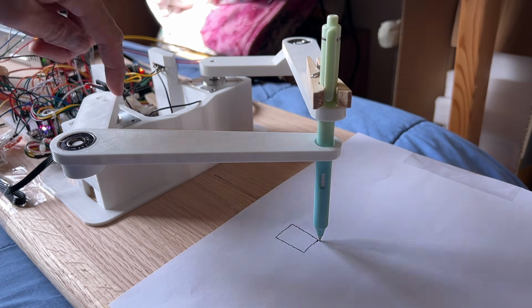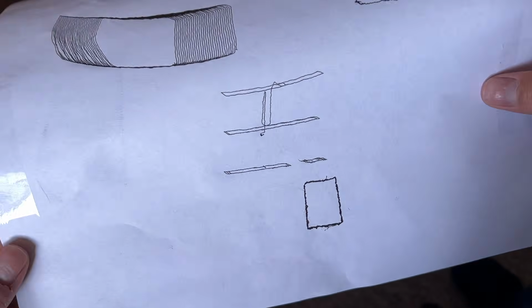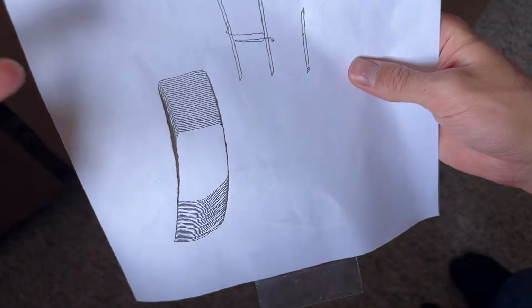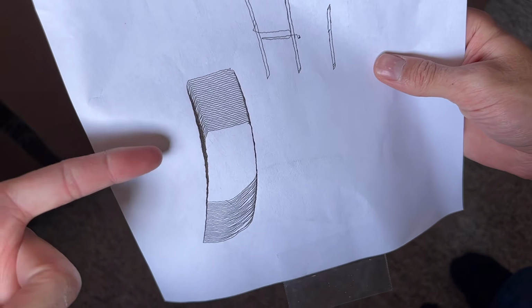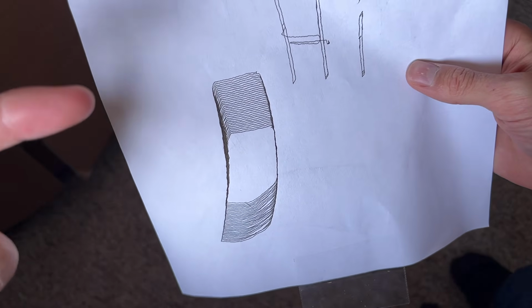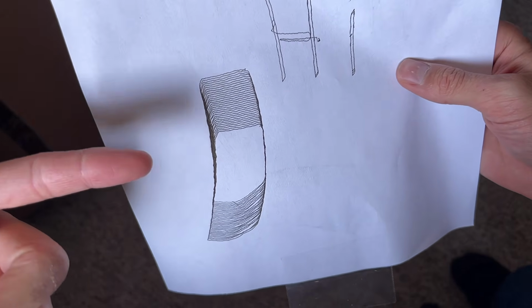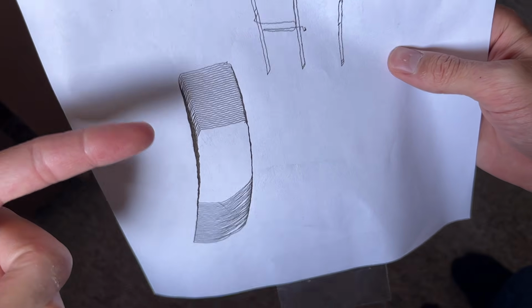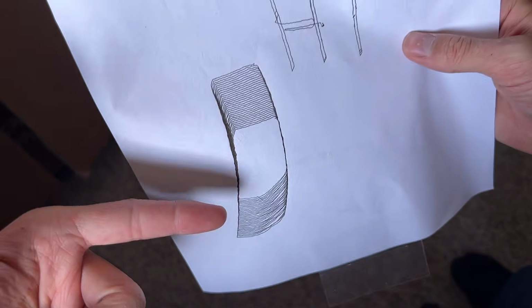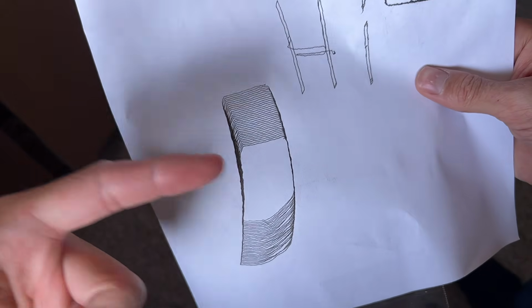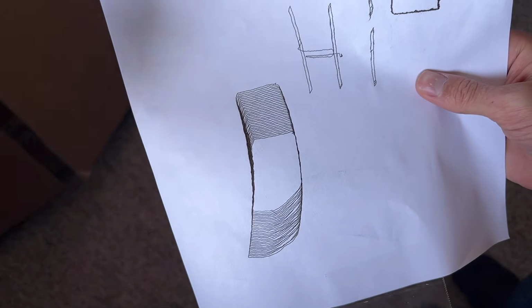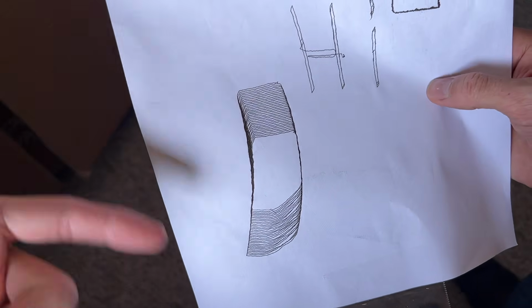Also, since we added the encoders inside of each motor right here, we're actually starting to get a lot more accurate readings. For example, this was a rectangle that the robot drew last week, and I had it basically just do this loop of drawing the same rectangle. However, it started to move the rectangle down to the bottom right here, and that was just because it thought it was in the same spot. However, the readings were just being thrown off every loop iteration.